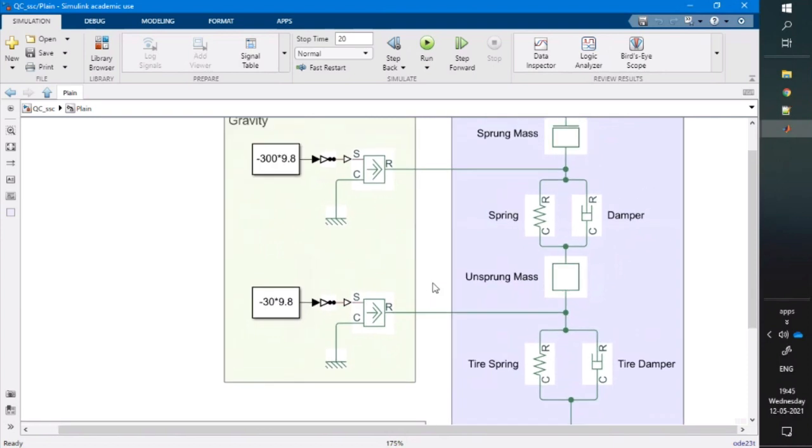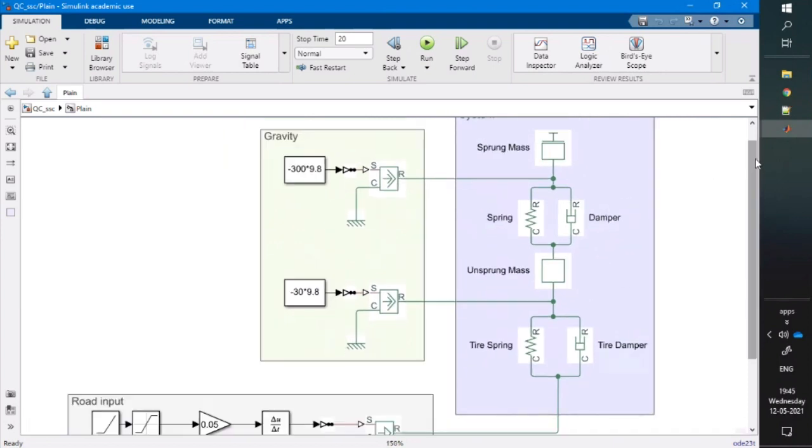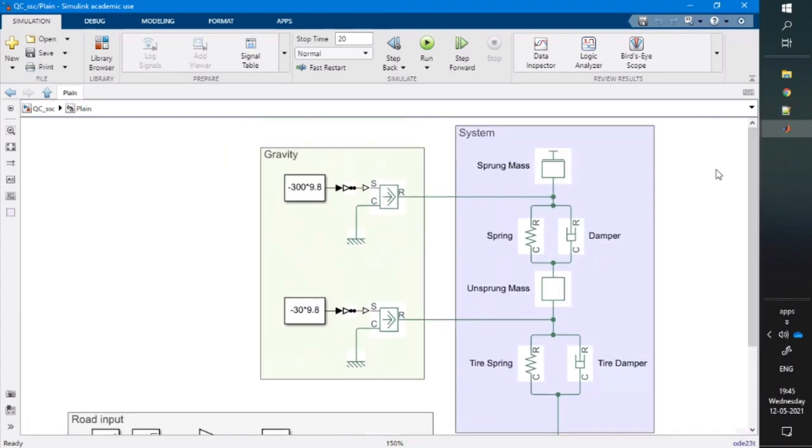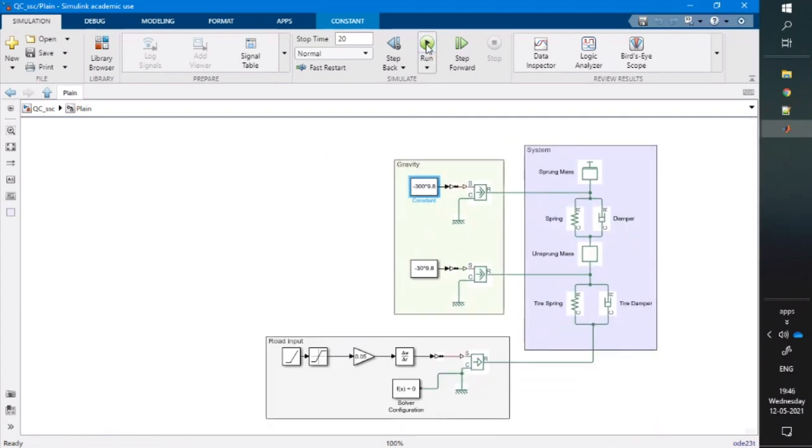We also need to include gravity. This is a diagram-based 2D modeling, so there is no directly available gravity option. Just multiply the mass by g and you directly get the gravity force on top. This is limited in dimensions. So let's simulate and check how this looks.